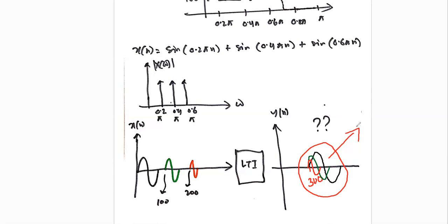So there is a term called noise due to the phase distortion. So this is called the phase distortion. Due to this kind of phenomenon, we have the phase distortion, and that is not permissible for the signal. That's why there is a problem in the IIR system. That's why people are thinking about the FIR system, though in case of the IIR system there are some advantages.